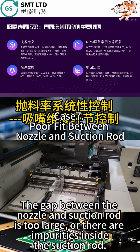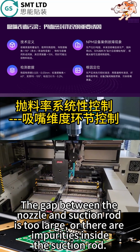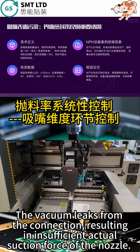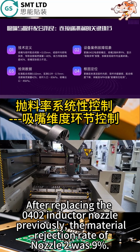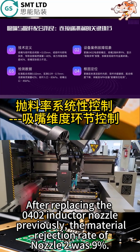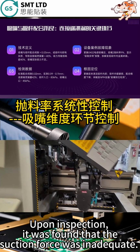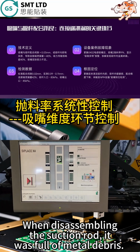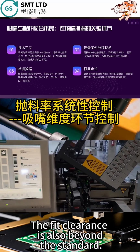The gap between the nozzle and suction rod is too large, or there are impurities inside the suction rod. The vacuum leaks from the connection, resulting in insufficient actual suction force of the nozzle. After replacing the overall nozzle previously, the material rejection rate of nozzle 2 was 9%. Upon inspection, it was found that the suction force was inadequate. When disassembling the suction rod, it was full of metal debris. The fit clearance is also beyond the standard.